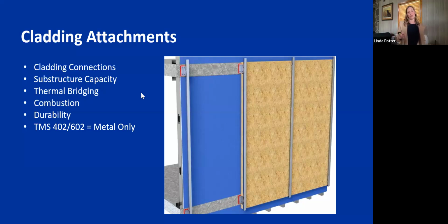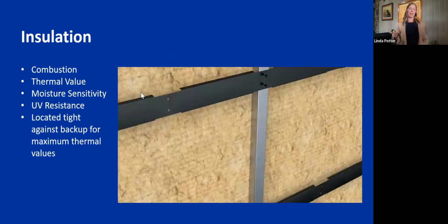The interesting thing about the masonry code is that it dictates that these be metal connections only at this point. And I know that we're thinking about that and we're addressing what else is on the market, but current code tells us those must be metal connections. Right now in the Rainscreen panel industry, there is nothing that dictates what it can or can't be. There's a lot of options for you to choose, or for your contractors to bring to you to say they want to use on this. And so all of this to say, it's part of why we need to really understand what we want to achieve and what exists out there to help us do that.